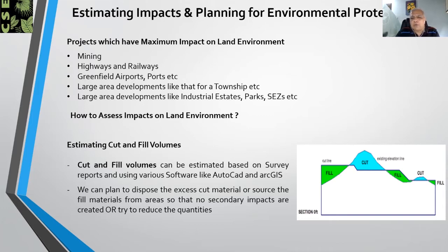And then using software like AutoCAD and GIS, we can find out the exact quantity of cut and fill volume, and even study some amount of the area beyond the particular site, so as to ensure that the natural drainage pattern will be changed to the minimum.